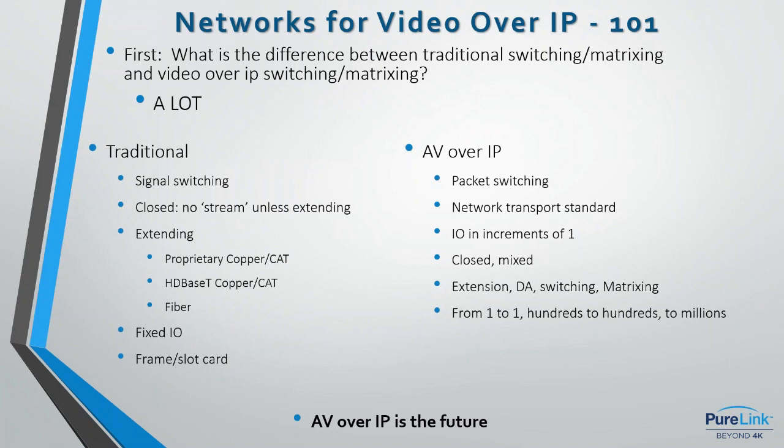And a great example here is on the extenders application. If I have a 1 source encoder and 1 display decoder, I can connect them directly together without a network switch, or I can connect them through a network switch. So I got 2 different choices there, and one of the advantages is I can double my extension distance going through a network switch. And just as a practical note, there are network switches that are sub $100 that will do that. And we'll talk about that when we get to network switches if I don't forget.